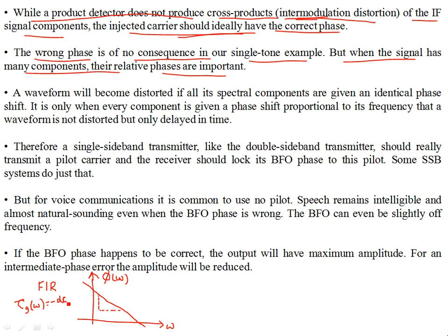What does this mean? This means that the frequency components that start together arrive together. That means they suffer no distortion. The time delay of each frequency component is constant with respect to the frequency. This quantity is known as the group delay.